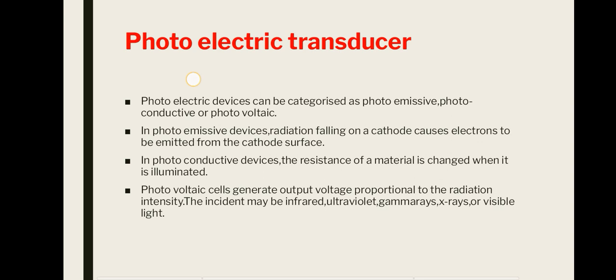When electrons moving at a high velocity strike an appropriate material, the material emits a greater number of electrons than it was struck with. In this device, the high velocity is achieved by the use of a high voltage between the anode and the cathode. The electrons emitted by the first dynode are then attracted to the second dynode, where the same action takes place again.